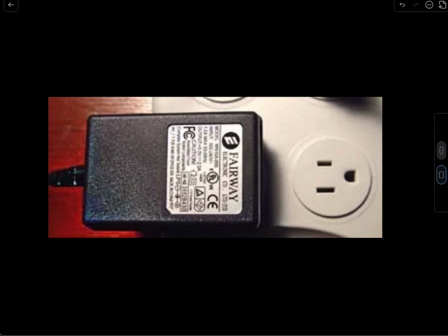And because of USB-C and power delivery, you will very seldom keep on seeing this wall charger being offered anymore, because they are noisy in terms of electronic noise that they can generate. They dissipate. They are less efficient than USB-C is, and they're bulkier, etc. So there's no reason for having this, and they're all fixed voltage, while USB-C can give you a menu of voltages and currents that you can take advantage of.